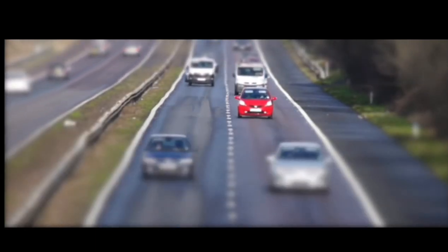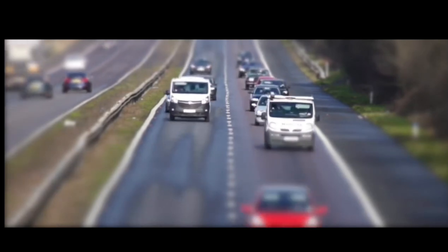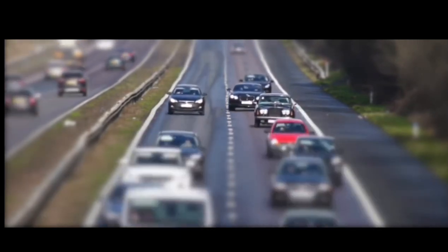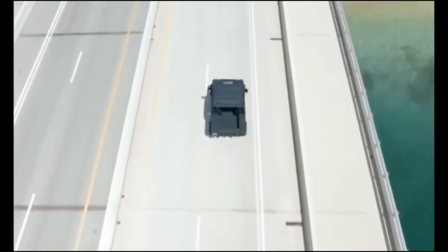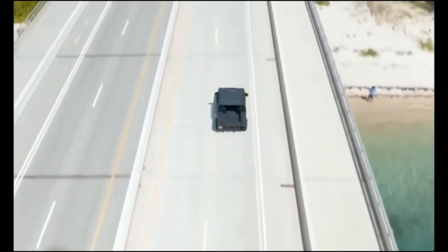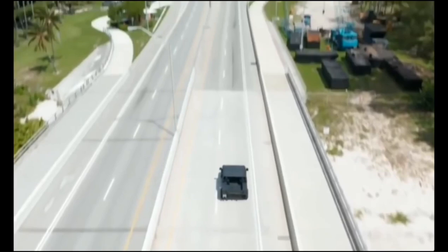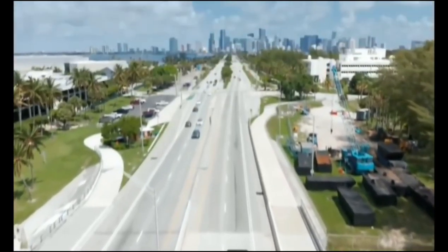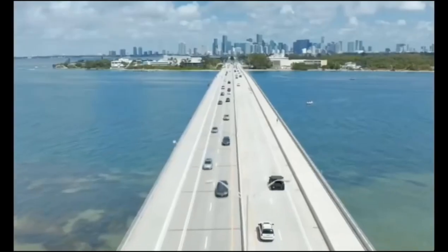Disadvantages: shorter lifespan, typically 10 to 20 years. Prone to deformation under heavy traffic. Affected by extreme temperatures, requires more frequent repairs. Rigid pavement. Rigid pavements are constructed using concrete slabs, sometimes reinforced with steel, and are designed to distribute loads over a wider area. Types of rigid pavement.